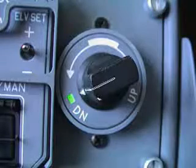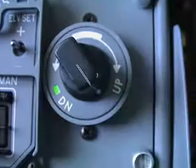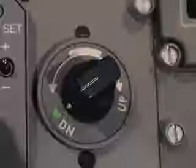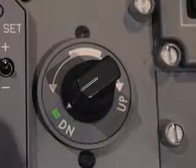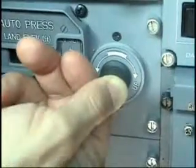The manual controller consists of a knob to select cabin rates between minus 1,500 feet per minute at down position and plus 2,500 feet per minute at up position when operating in manual mode. When operating in auto mode, the knob must be set to down. To dump the cabin in manual mode, the selector knob must be set to full up position.